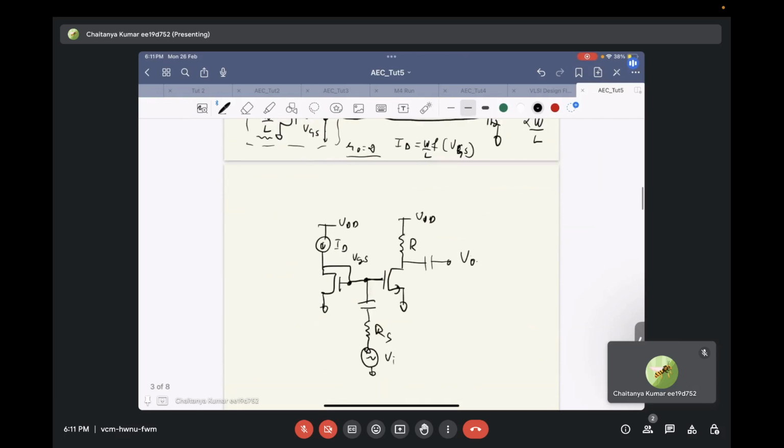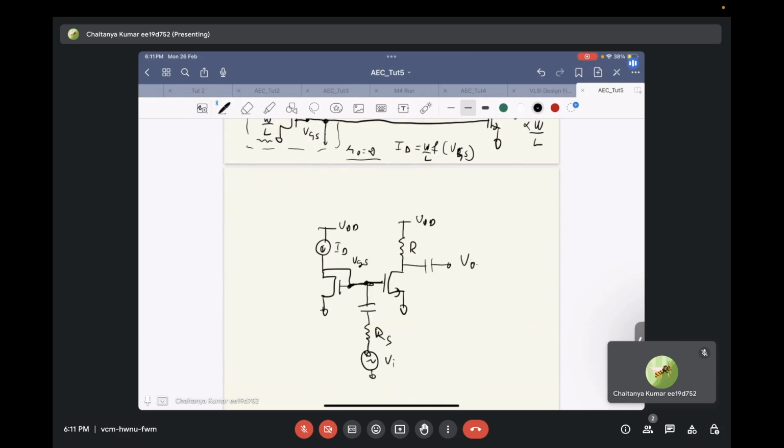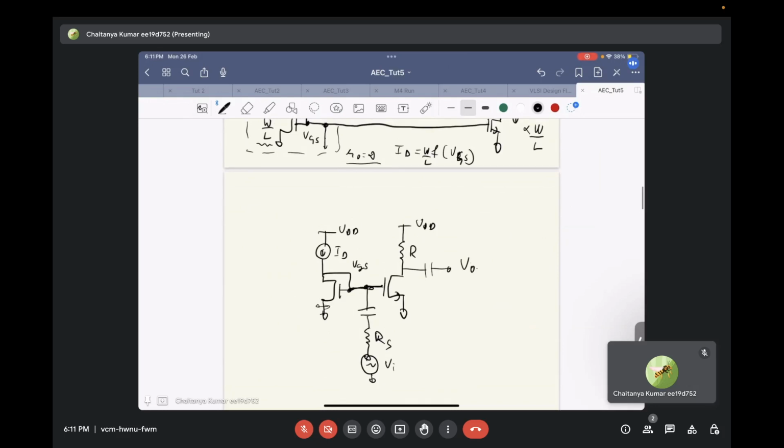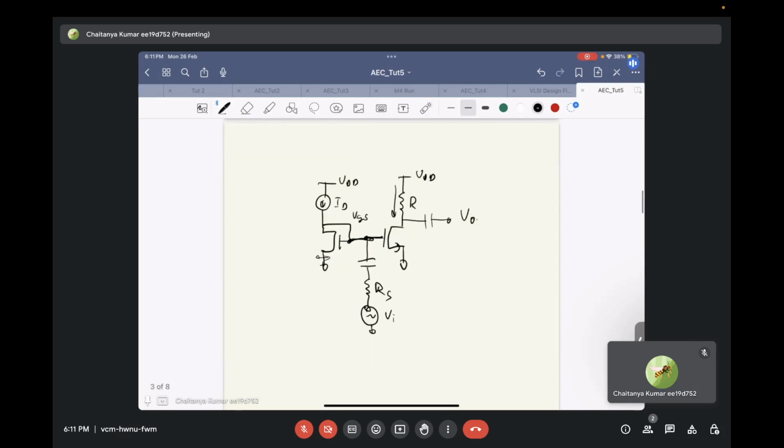So with this, the VGS, based on the process and temperature variation of this particular transistor, keeps on varying so that the current that flows through the input device remains constant, hence keeping its parameters constant. So this is basically the use case of our current sources.